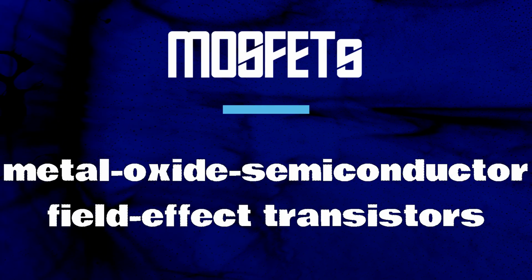In the real world, logic gates are built primarily using diodes or transistors. A transistor acts like a switch or a gate for electronic signals. They open and close these gates multiple times a second and ensure that a circuit is on, represented by a 1 if current is flowing, or that it's off, represented by a 0 if it isn't. Most of them are made from MOSFETs, or metal oxide semiconductor field effect transistors. These are the most common type of transistors used today and are like a valve for electricity. They have one input connection called the gate, which acts like a switch to control the 2 outputs.